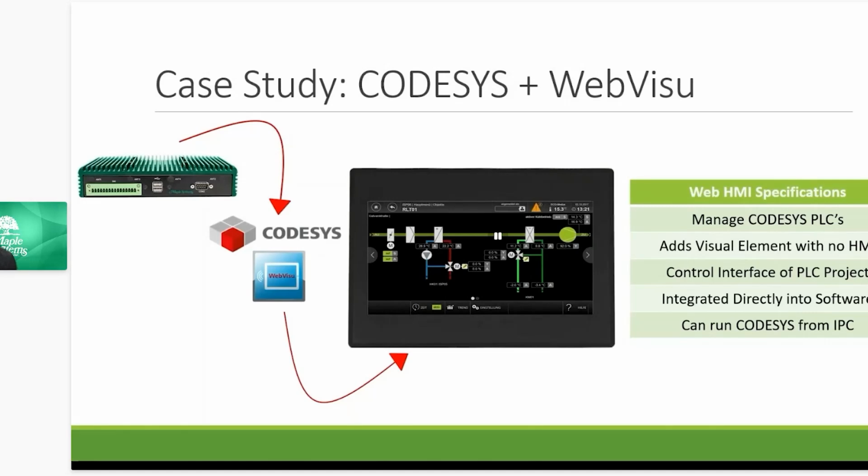What you can do and what the benefit with these web HMIs is that you have your main SCADA platform on an IPC up in a control room or wherever you have it in your facility. And without having to buy another IPC or an industrial monitor, you can extend that display, and not just display, but full control throughout your facility in a cost-effective manner with these web HMIs. On top of that, these are high brightness web HMIs, so they're sunlight readable, and they are Class 1 Div 2 as well. So they really fit into that industrial automation setup for a SCADA system.